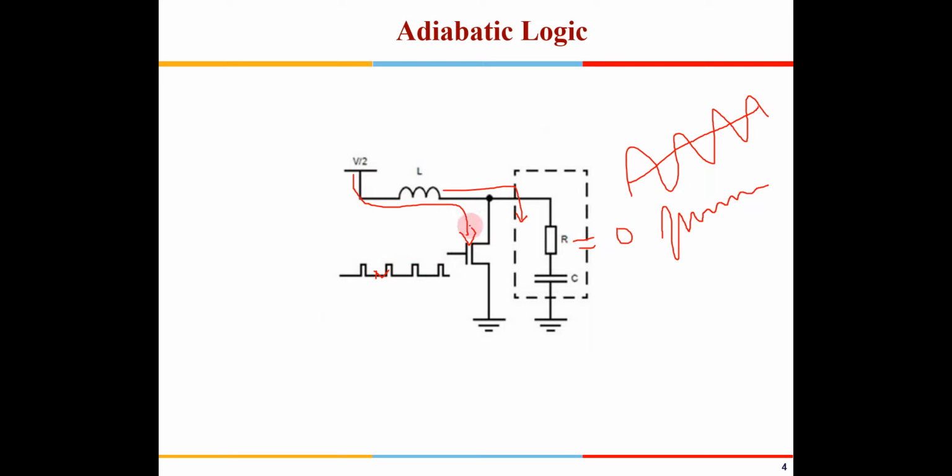But overall, if you see, as compared to the static circuit, this is generally oscillating. Only a small amount of charge needs to be taken from VDD periodically. Okay, so at say 1 kilohertz or lesser than that, some small amount of charge needs to be recovered into the circuit because of the losses which are not under our control. But overall, if you see here, adiabatic circuits have a much lesser power consumption than the corresponding CMOS.